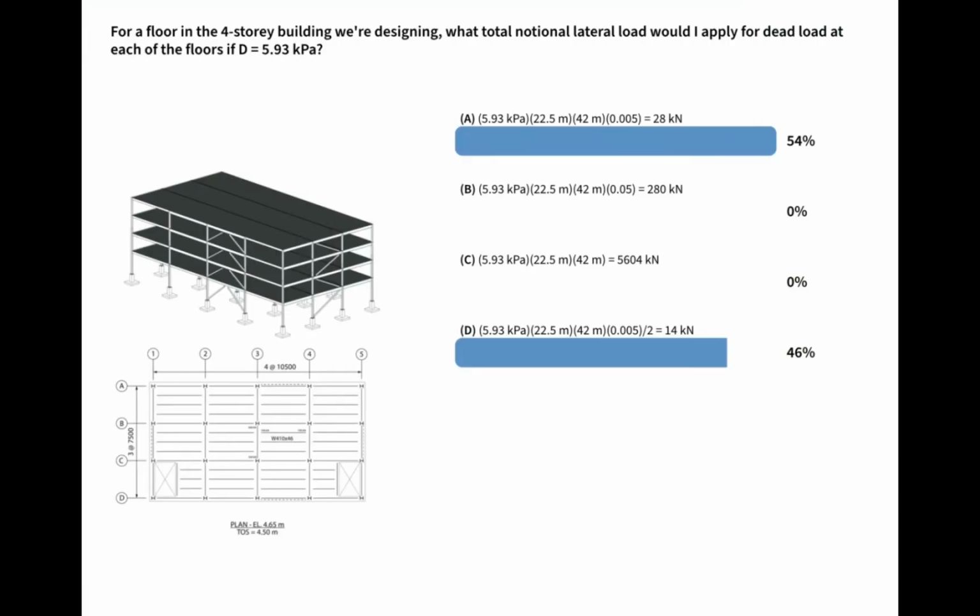I didn't want to get into that necessarily in this course, but usually this X denotes an opening. That might be for a stairwell. It might be for an elevator shaft. It might be for any reason you might have an opening there. And so technically there's probably no concrete there, but if you've got a stairwell, it's probably similar enough to the dead load that it would be similar. So it might or might not. I'm assuming for the purposes of this course that in terms of the opening, there's maybe some stairs and it's about the same dead load distributed over that area, but it might not be. It might have an opening that's an atrium space, or for an elevator that would change slightly the total dead load at that level. Any other questions?